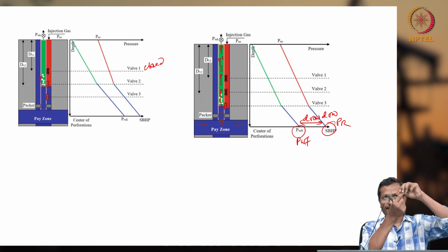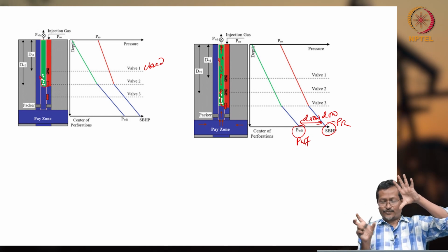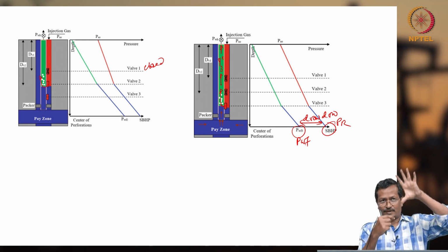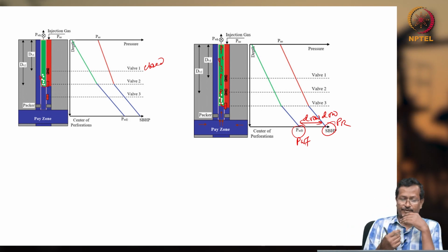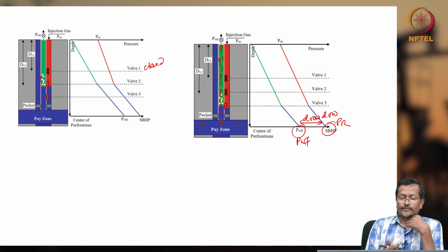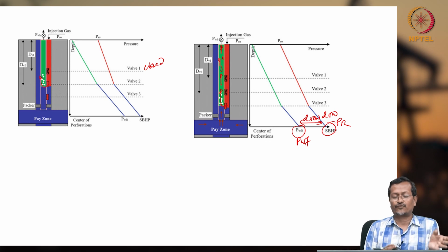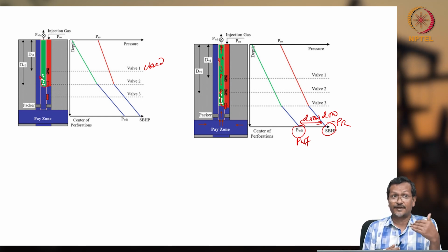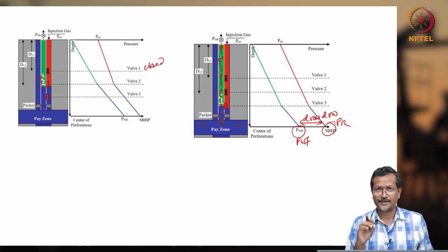and the second valve gets lots of gas, again further reducing the whole column weight. Then you get more drawdown, more fluid will be entering, and slowly you get a lower hydrostatic column and more fluid entering, so you get more production. And if you want more production, let us say someone becomes too optimistic and uses a very high flow rate of gas, in that case you may not get optimal production; rather your production rate can actually reduce. So, you must have the optimal production rate and optimal depth of valve, then you will get production.